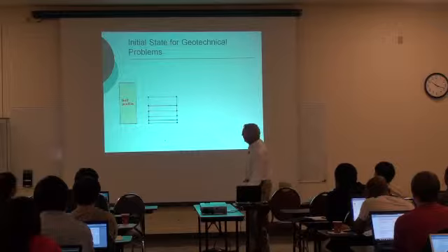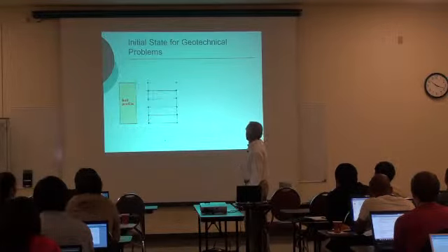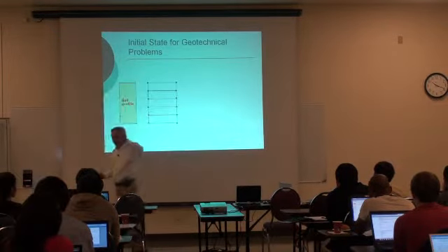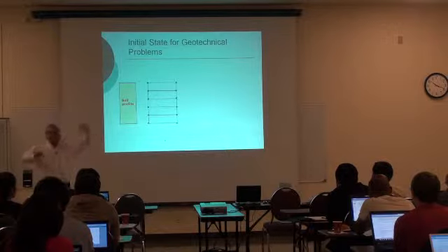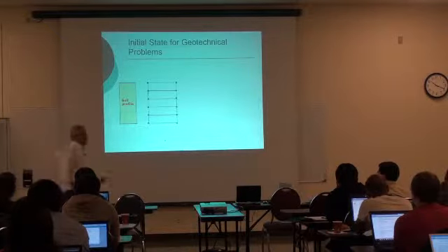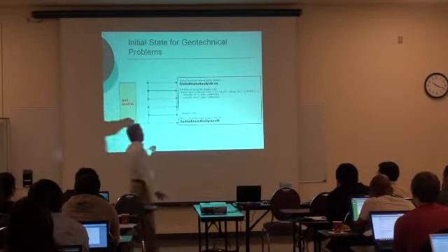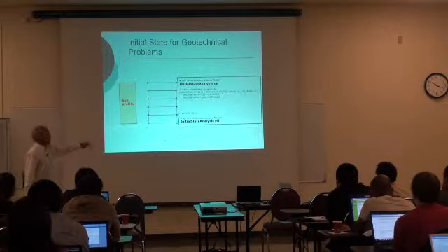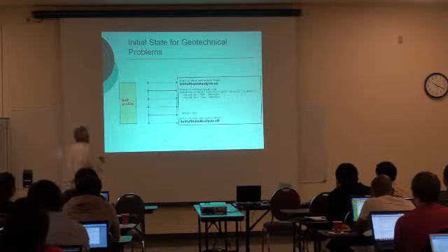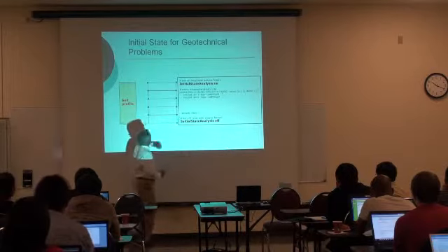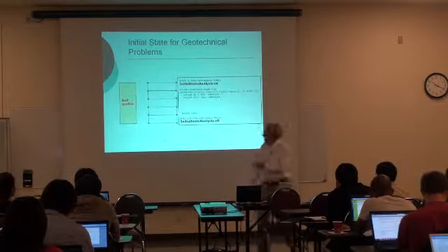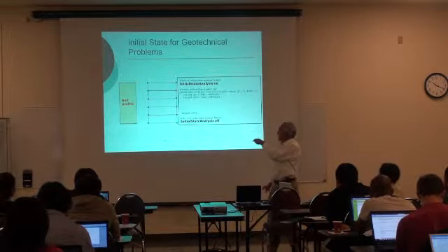So what we have done is to include a command that removes that deformation and includes it in the elements as an initial value that will be carried on in the analysis, but you will not see it. How do you do that? It's very easy. You just call initial state analysis on, then you perform all your steps where you apply the load, and once you have applied gravity, you say, okay, initial state analysis off, and that immediately removes the displacements, and you can continue your analysis as if your soil was exactly at this level here.